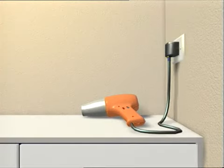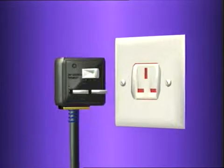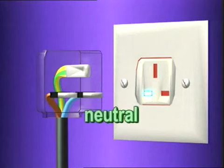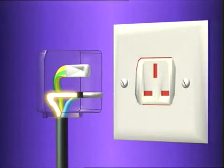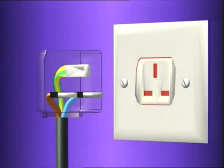Appliances using AC power supply have to get electricity through a plug. This is a common 3-pin plug. The pin in blue on the right of the plug is inserted in the hole for the unchanged voltage. This is known as the neutral pin. The pin in brown is inserted in the hole for the ever-changing voltage. This is known as the live pin. The pin on the top is connected to the earth wire.